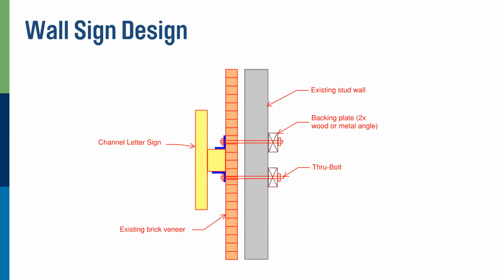So what you have to do is put some sort of blocking behind the stud, called a backing plate. If it's wood frame construction, you can put a 2x4 or 2x6 behind it, or you can put a metal angle, a little 2x2 angle, or a piece of unistrut, which works really well. You can buy all this at Home Depot, and you attach that to the inside of your metal stud so that it's now part of the structure. So you've just enhanced your existing structural, and now you have something continuous to attach to, so that your fastening pattern, your bolting pattern, aligns.